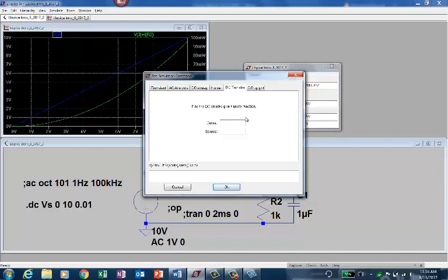If you have taken a circuit class, it is a Thevenin's equivalent voltage. If you look through a terminal, whatever terminal you want, with respect to the input, you want to see the equivalent voltage and the resistance. Say the output is V out equal to V3, and your input is VS. You want to see the Thevenin's equivalent circuit. That means if you're looking into V3 across the 3, you're going to see a resistance and a voltage source. That's what you're looking for.